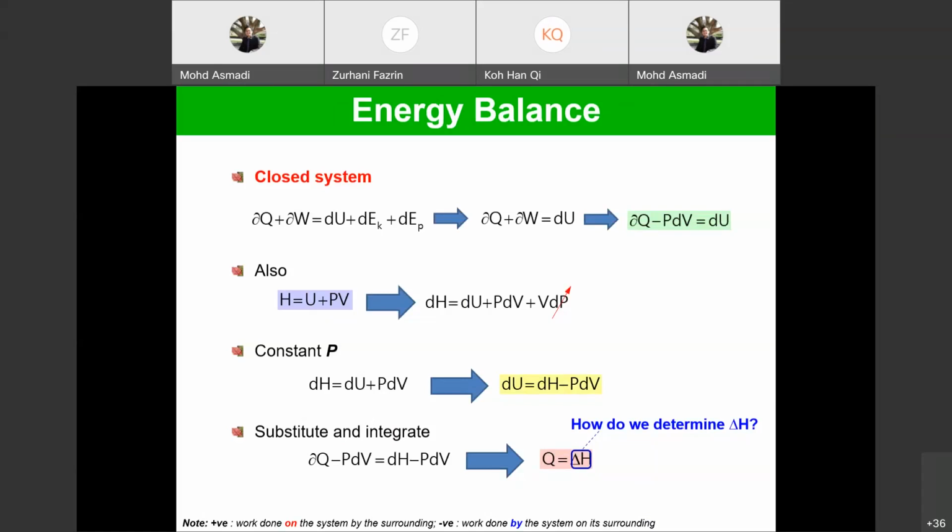but the problem is how can we calculate the change in enthalpy? This is what we have to find. If it is an ideal gas, we just use m Cp dT, so dT is just delta T, T2 minus T1. But how about very high pressure, right? A wide range of temperature and also pressure. How can we calculate that one? We need the integration, and we also have a special equation. It's very long, so you have to know these equations.